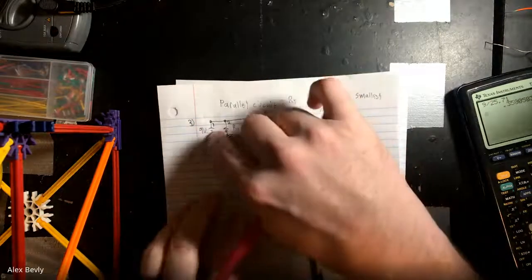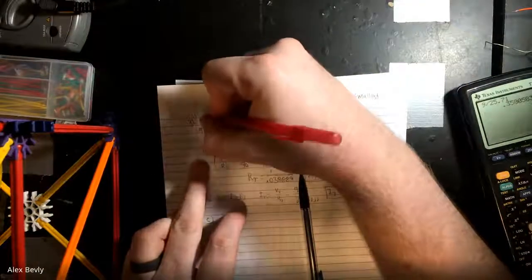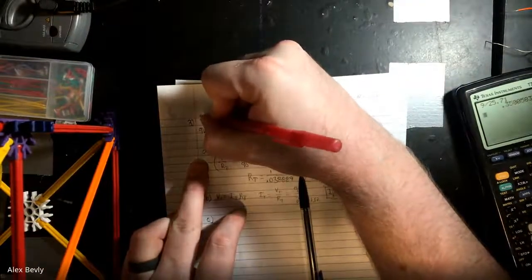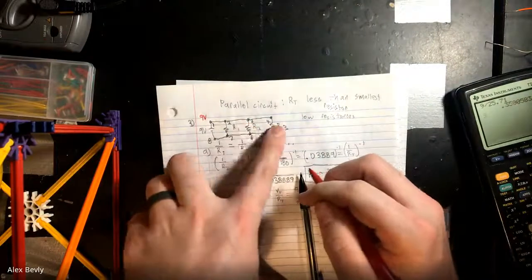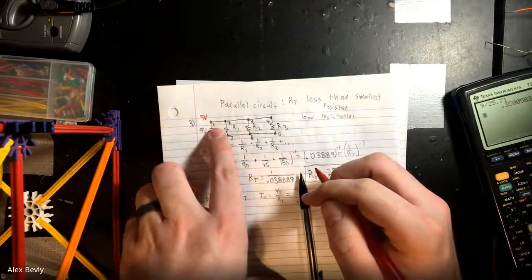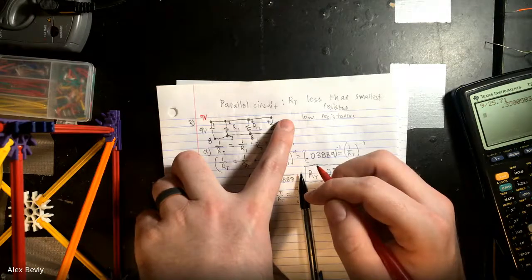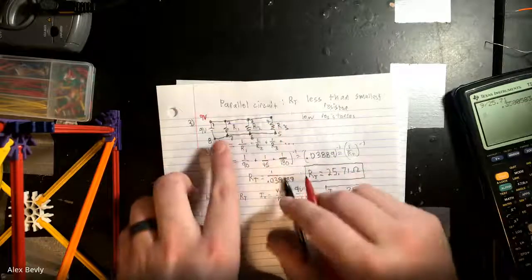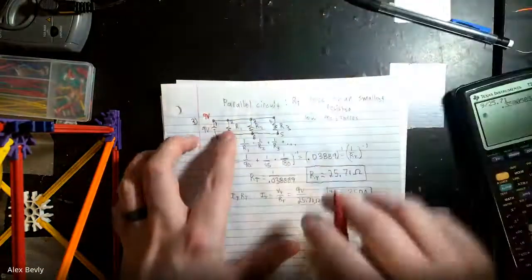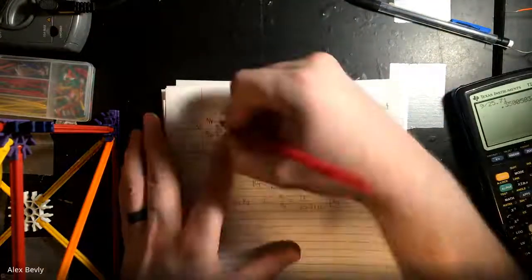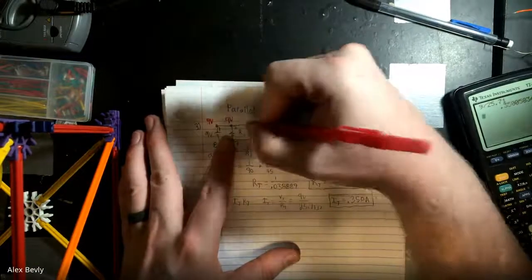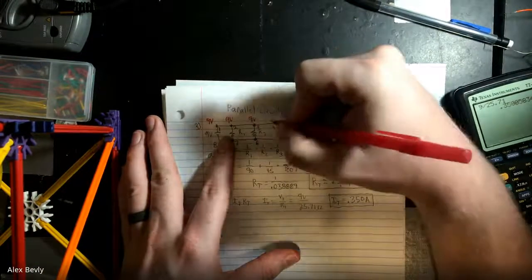So here, I've just gone through the battery, so I'm at 9 volts. Are there any resistors on this top part right here? No resistors at all. So if there's no resistors, just these perfect magical wires without resistance, that means my voltage isn't dropping across this top.